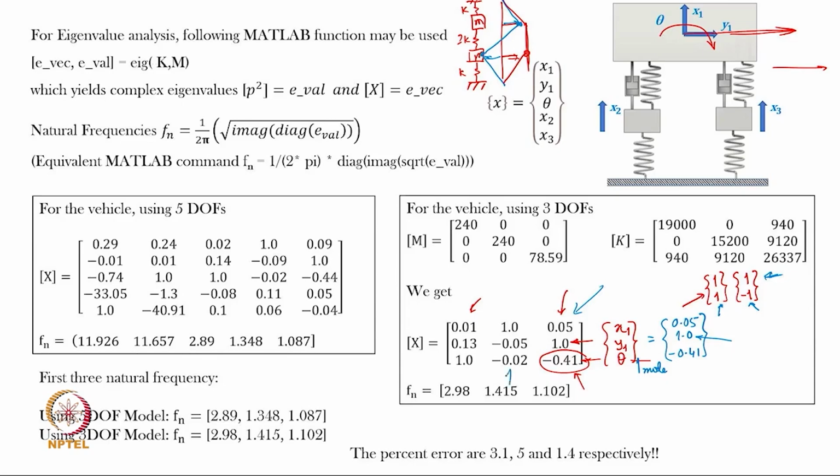In the second mode, at some higher natural frequency, now you have a vertical bounce motion taking place. Okay. And because the CG here is not assumed to be in the center of the span, as a general case you have a coupled pitch and bounce motion possible. Which means that if you try to lift the chassis up at the CG, it is going to also tilt, and here the CG position could be such that you still have a vertical x1 motion.